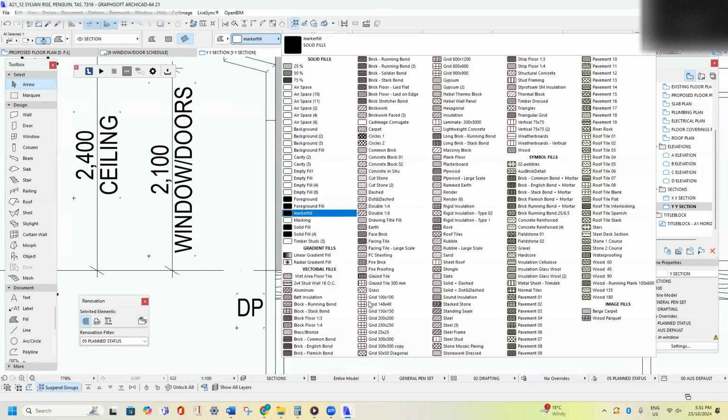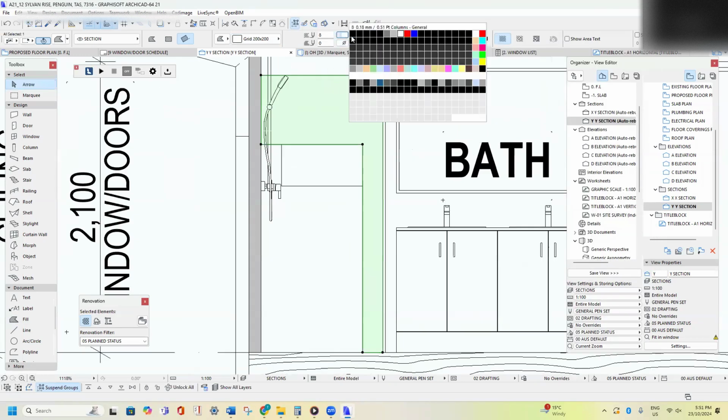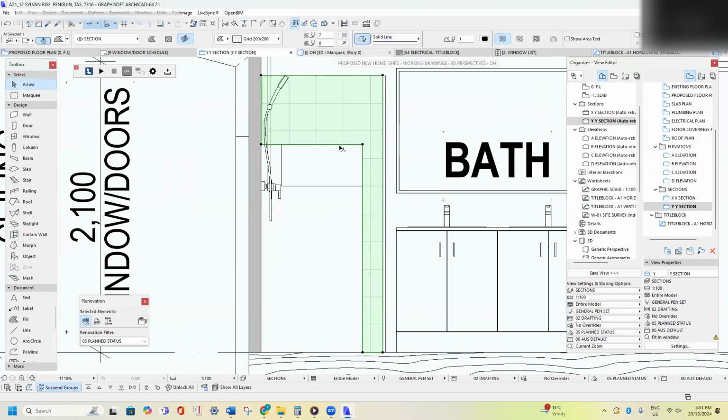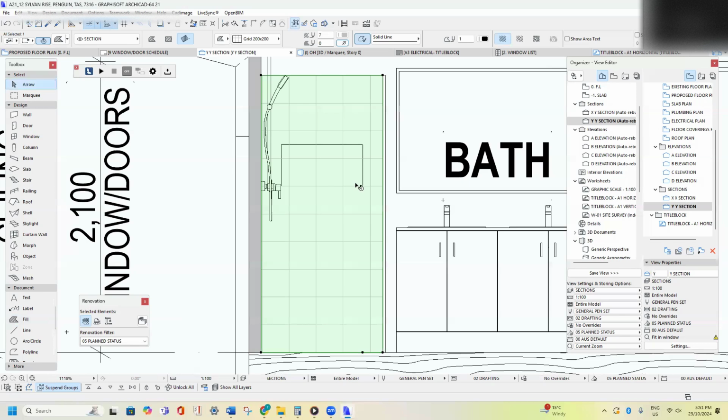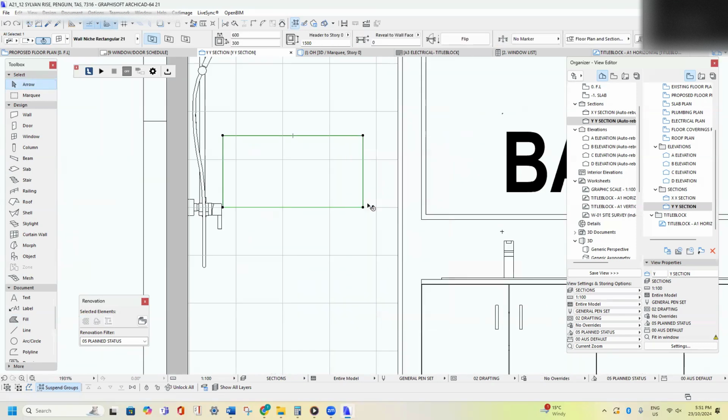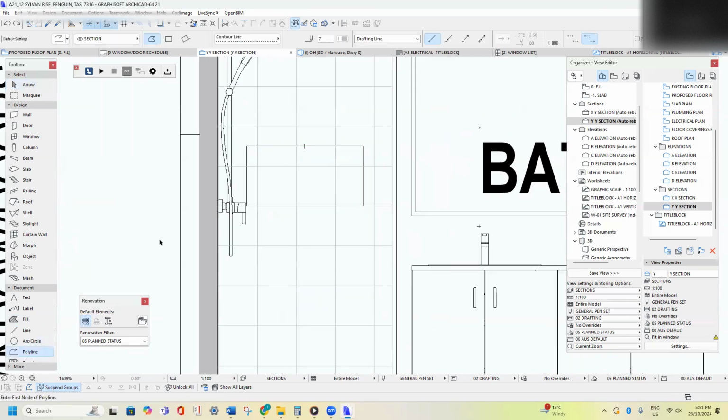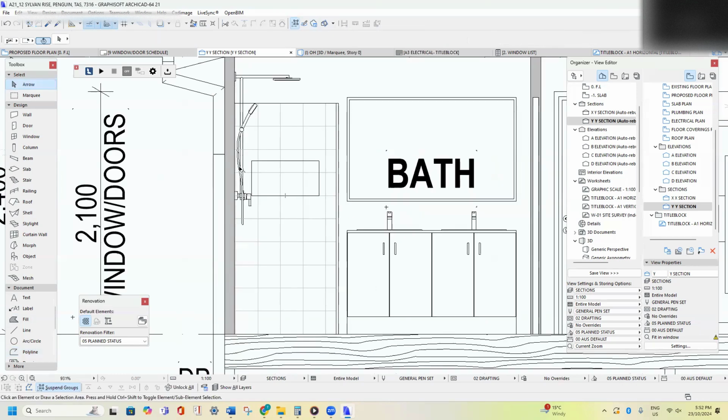So what we'll do is we'll change this to 200 by 200 tiles. We'll make this gray and we can actually extend that all the way down. If we make this at 0 on this option, it'll be see-through, meaning you can see that. If you click on that and make that white, you won't see anything behind it. So what I might actually do is just click the polyline, change it to black. It's on section. Click that option and click. I just need that bottom of that line to show up.